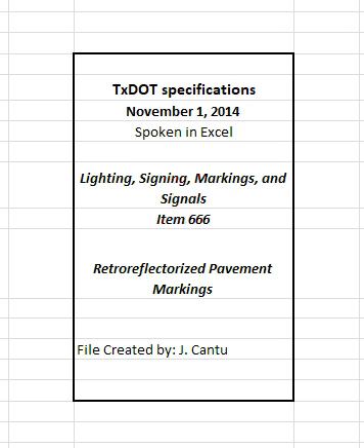The use of pans, aprons, or similar appliances which the die overruns will not be permitted for longitudinal striping applications. Provide a handheld thermometer capable of measuring the temperature of the marking material when applying Type 1 material.